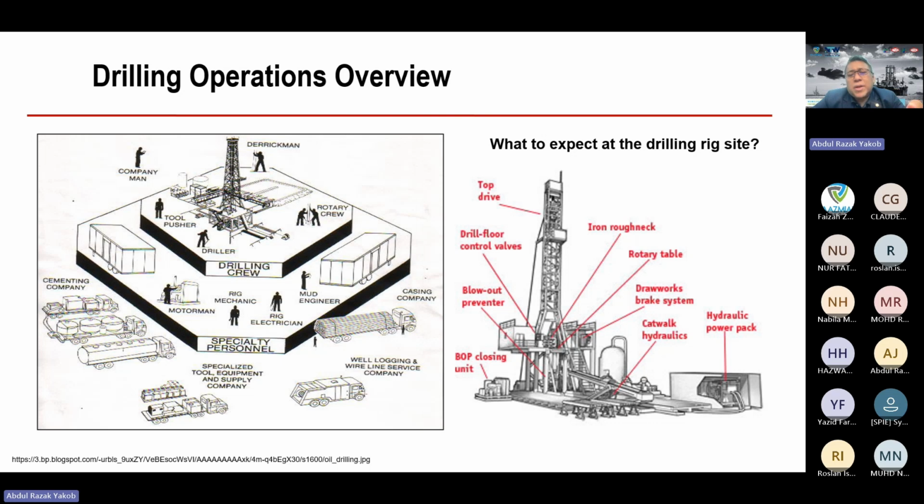So the derrick over here, the blowout preventer that we have over here is so important, because in the Deepwater Horizon, that's what failed. That's what failed, that allowed the blowout to reach the surface. The blowout was supposed to be contained at the formation level, before it goes up to the sea. But once it goes up to the sea, it basically cannot be helped anymore. Once the bottom is already breached, it will definitely sink your drilling rig. Yeah.